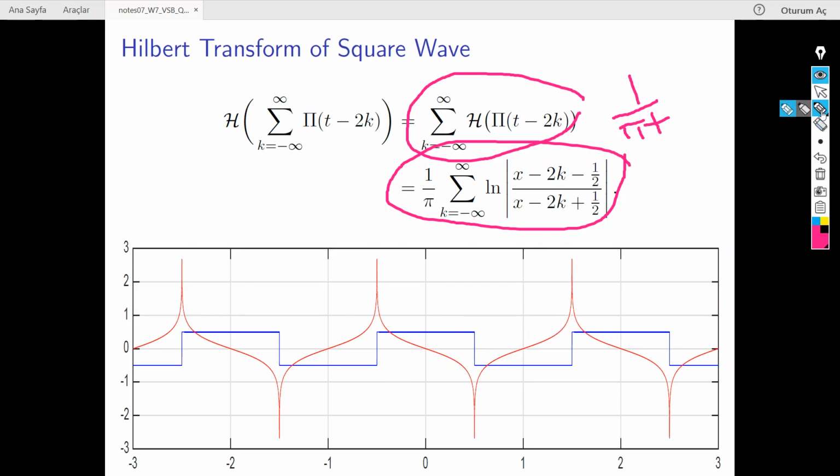Now, this Hilbert transform can be used to represent the mathematical modeling of single sideband modulation, no more, no less. So it's just a mathematical trick to represent the equation of the modulation. So this is basically the single sideband in the mathematical form, and we saw it in the graphical form. Now let's go and see vestigial sideband in both math and graphics.